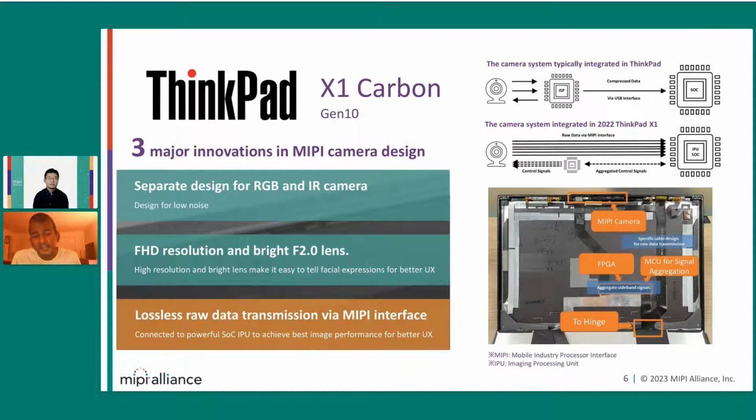Absolutely. There's a question on the chat from Ethan, and this is something we presented in the first two webinars under the umbrella of USL. We are presently exploring two flavors of USL. One is using D-PHY embedded clock mode. It's a two-wire solution, again, facilitating the longer reach. And the second exploration is using the ternary solution, using C-PHY 16B or 7S.